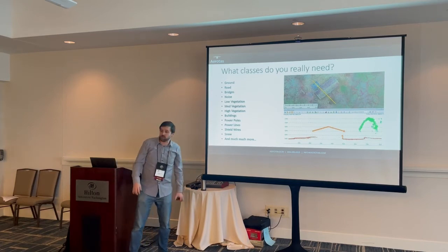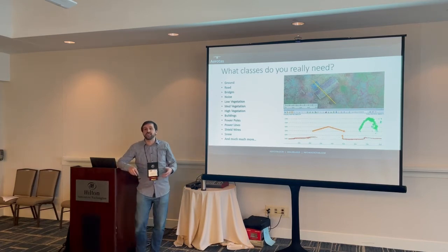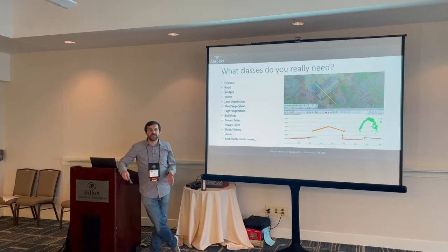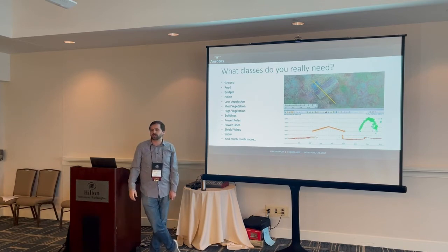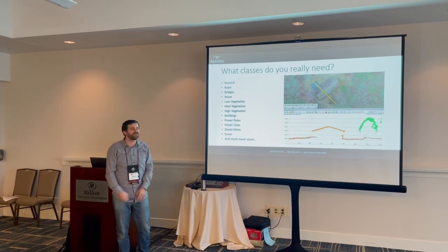There are some situations where there are software packages that do need classifications, but even then, typically it's like, okay, we need these classes because we're measuring the distance from the transmission line to other structures. So we need to know vegetation, structures, and ground. And those are the only points that we need. Cool, then only classify those. Don't waste your time on all of the other things.